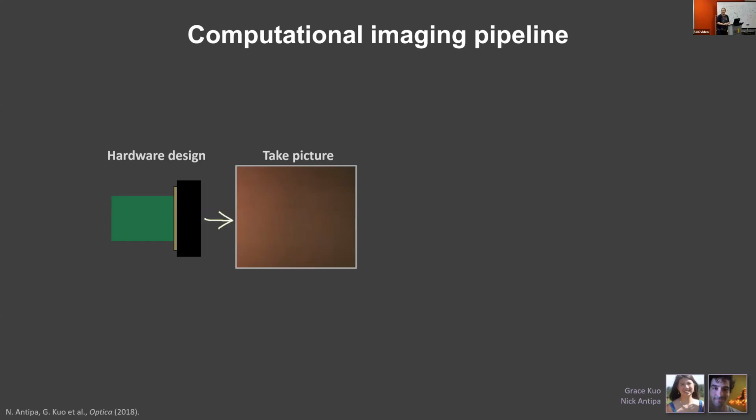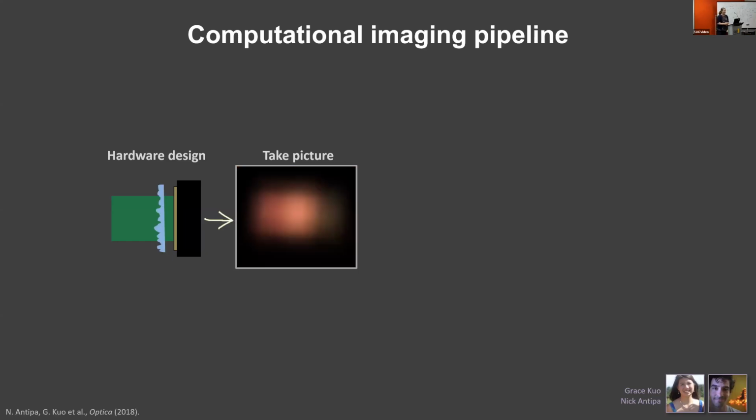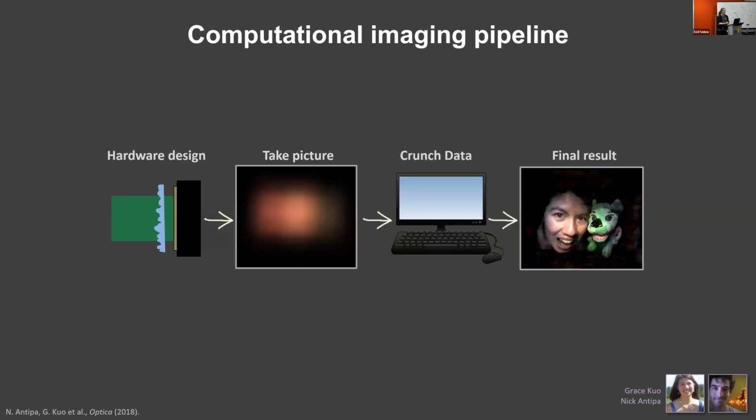Maybe. In practice, this inverse problem is too ill-posed. DiffuserCam is the idea that if we put just a bumpy piece of plastic, like a diffuser, you could use Scotch tape. We started the whole project with the privacy glass stickers, the stickers you put on your windows so your neighbors can't see in. You just put that on top of the cover glass of the sensor and take a picture that looks like garbage, but now it's structured garbage and I can reconstruct a nice image from it.